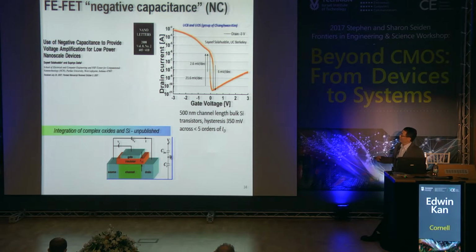So negative capacitance was first presented actually quite early, in 2008, hoping to achieve sharper switching transistors without a memory effect. It's meant for a logic device. Okay? The idea is just that the gate stack will have a ferroelectric and then a dielectric. That has been proposed for almost 10 years now, something that they hope to observe such a sharp switching.